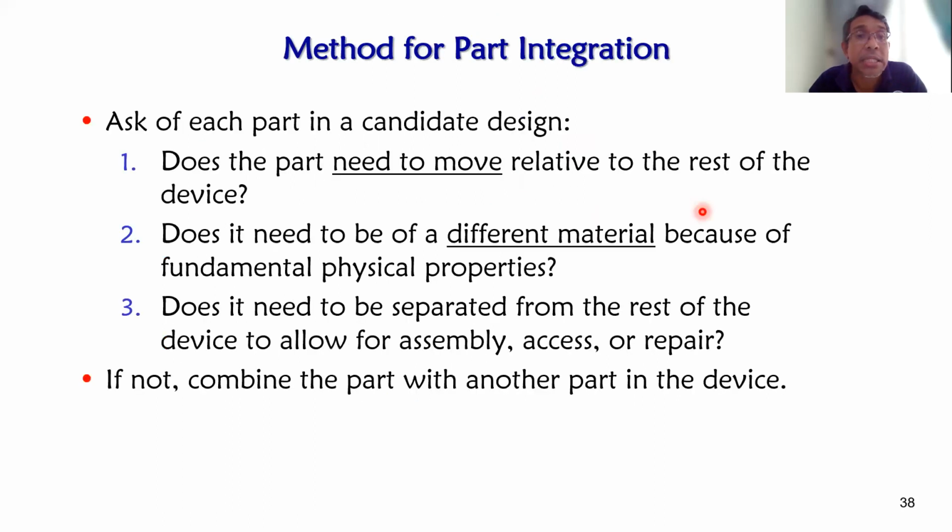And then methods for integration. So you have several methods in part integration. You need to always ask of the candidate design: does the part need to move? Does it need to be a different material? Does it need to be separate?